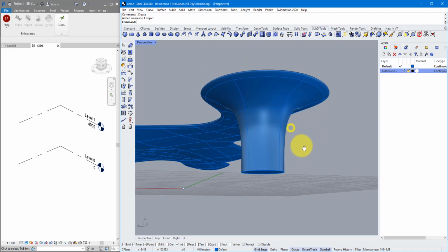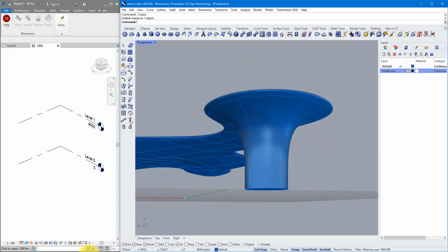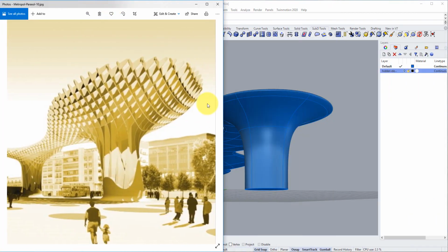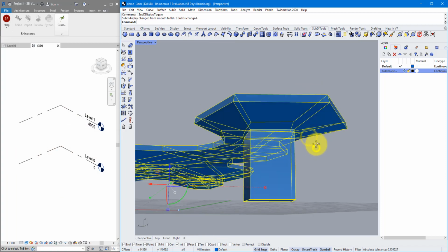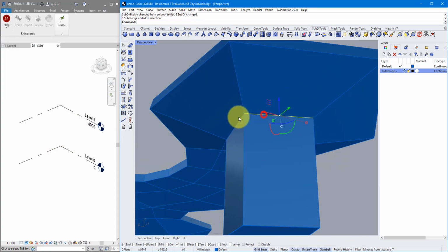That's more or less very similar to our column now. But if you look closely, the fillet amount here is a bit too much. The column in our reference project actually goes up for a longer distance before it starts to widen and merge with the roof. That's easy to fix. We can go back here now and select these 4 lines.